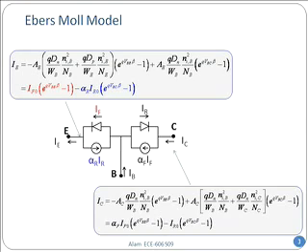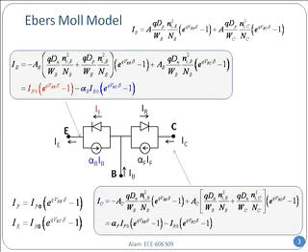It can recombine, that's fine. If it recombines, one component will go up, another component will go down. But so long as electrons are not destroyed, they can recombine, not destroyed, then the sum of the current must be equal to 0, because whatever goes in, in some form, electron form or hole form, it must come out. And this is the definition, and that's the base current.